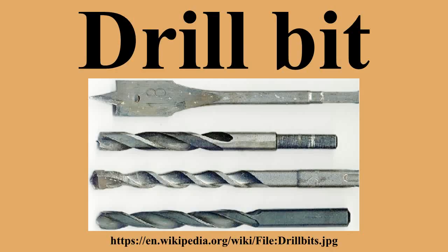The lip angle determines the amount of support provided to the cutting edge. A greater lip angle will cause the bit to cut more aggressively under the same amount of point pressure as a bit with a smaller lip angle. Both conditions can cause binding, wear, and eventual catastrophic failure of the tool. The proper amount of lip clearance is determined by the point angle.